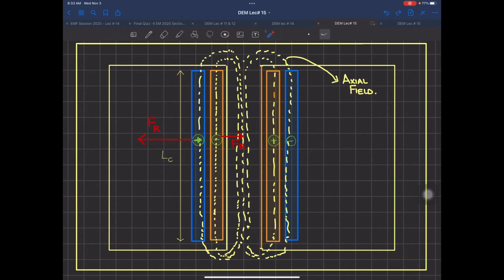And if the spacers in the winding, whether it is a disc winding or even some concentrated coil winding, whatever winding, if the spacers do not have that much mechanical stability, the force is going to crumble it. So it is very important that the inner winding should withstand the crushing force of a transformer. And the outside winding, which is certainly the high voltage winding, has to be fitted with some bracing.